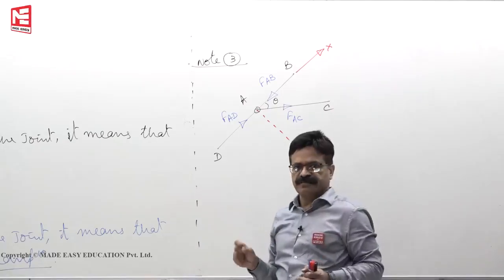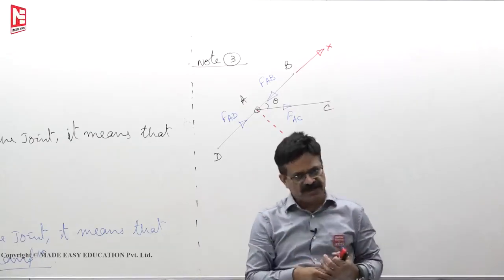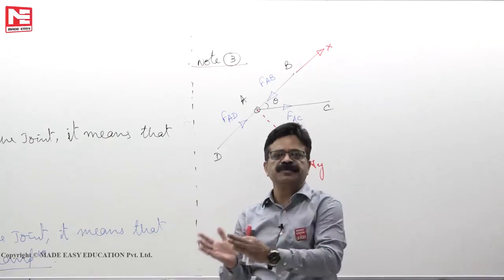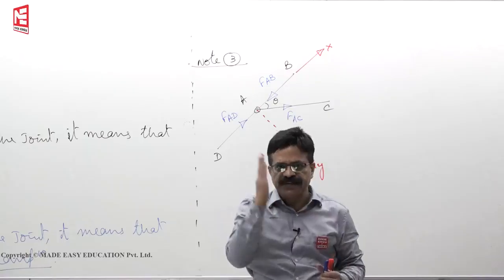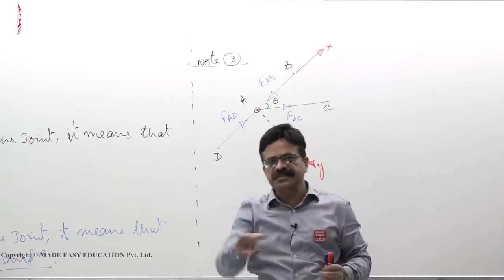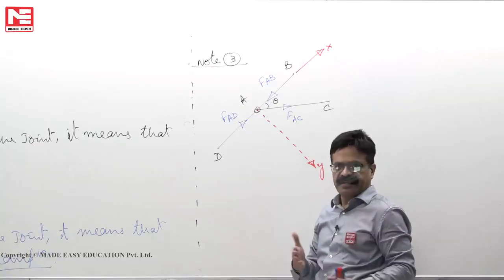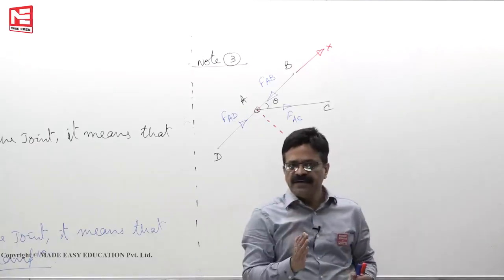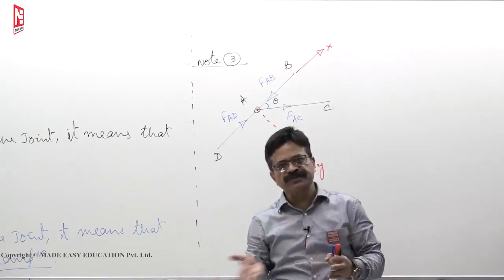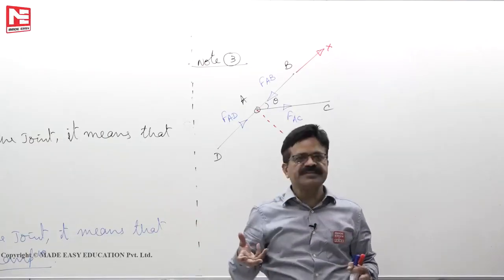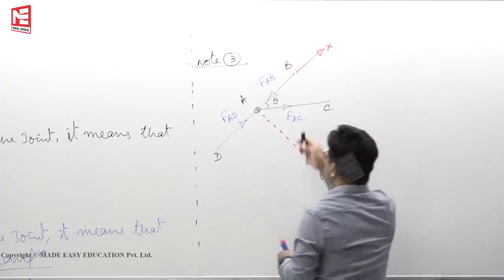Component of a force means what? In first year engineering mechanics we have studied the effect of the force in a particular direction. So if a force is acting like this, what is the effect of that force in the other direction, say? That means the component we are finding. We also learned that any force cannot have a component in its perpendicular direction. That means that force has no influence in the perpendicular direction. Rotational effect will be there, but direct action will not be there.